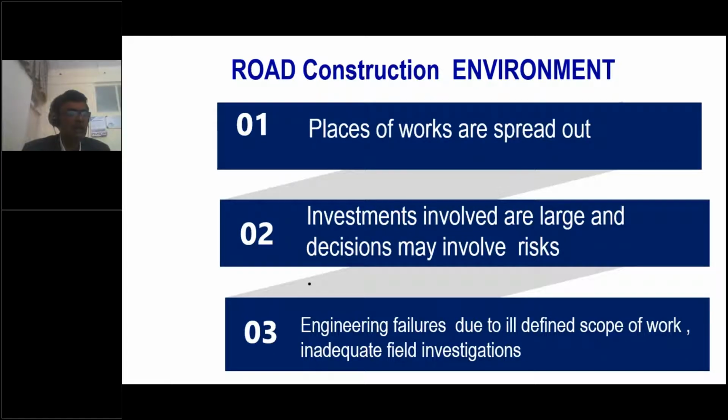So much care is taken, but in spite of that, when we actually start the execution in construction, maybe my CBR at chainage 1.1 is, as per the DPR, truly taken from this sample, I have tested it, my CBR comes to 5, or 6, whatever it is. Then based on that, the designer would have designed the pavement, and as a constructor, that is what I am executing at the site. I have mobilized everything to the site and am just doing my work, and suddenly I find that the soil at that particular chainage is not as per my DPR. DPR says it is 5, and now it is, let's say, 2.